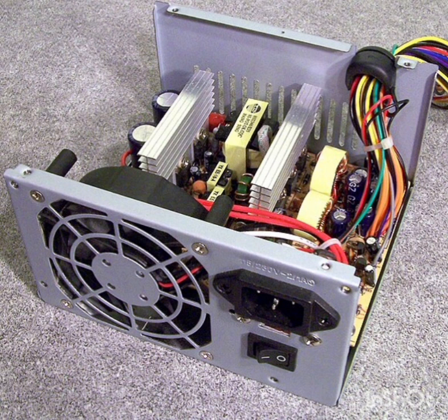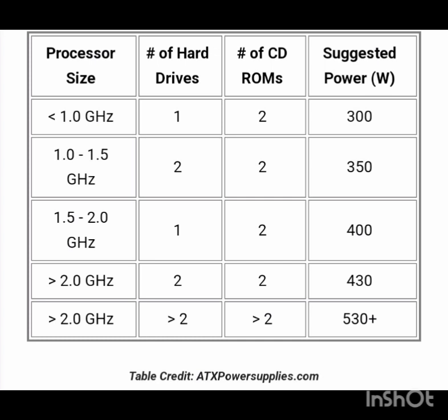Then there is output power. It is the power in watts delivered to the load. The rated power of the power supply must match the power requirements of the system, as an undersized device will cause power failures and computer rebooting. It is acceptable to use a power supply with an output power that exceeds the requirements of the application, as most are designed to step down the amount of power demanded from them. This chart provides suggestions for power supply wattage based on computer system size.